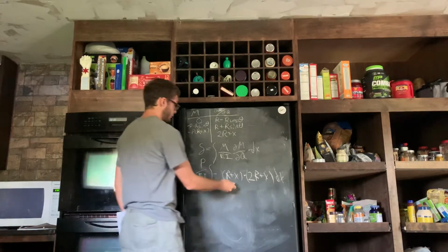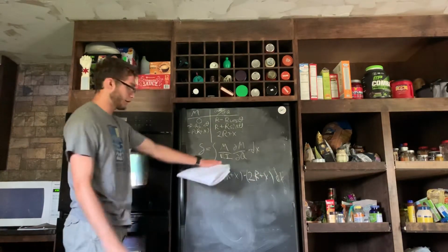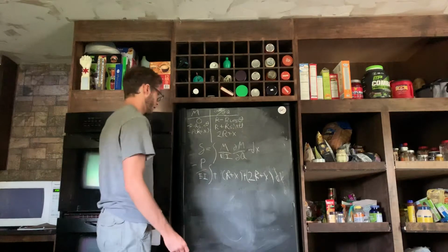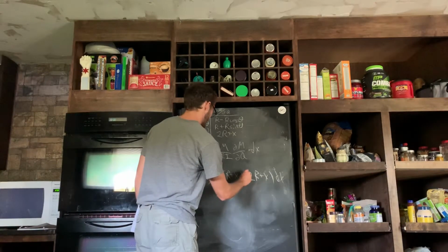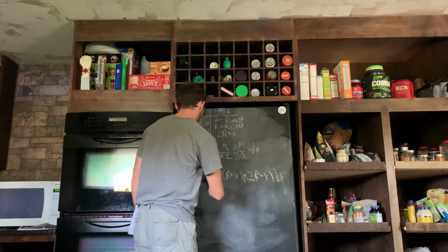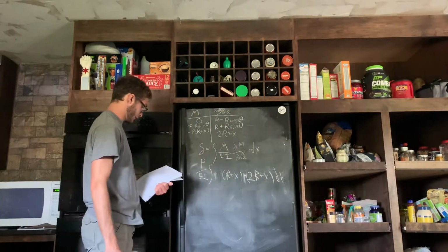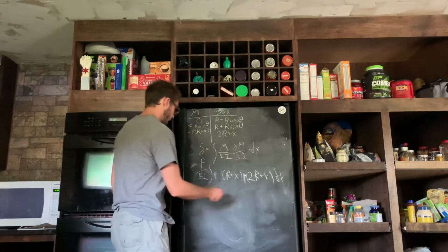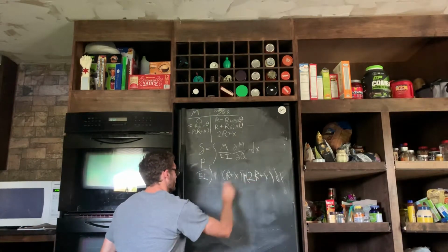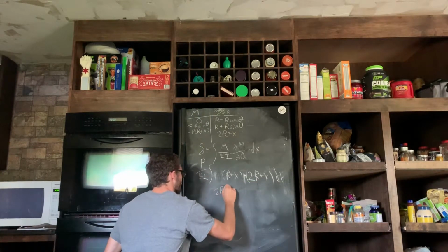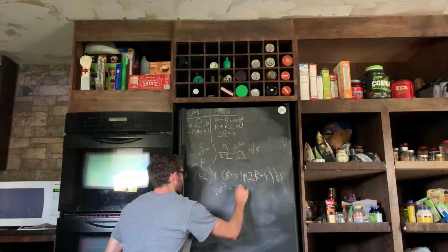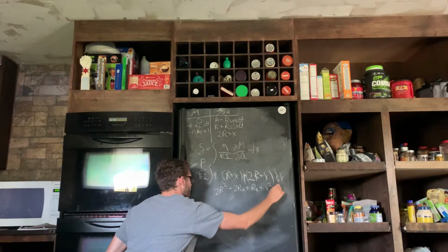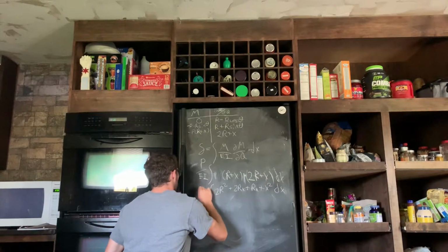So inside we have 2 equations with respect to x. They're both negative, so let's just pull out the negative sign as well, make it a little bit easy. Oh wait, no, that's a multiplication. No, it's not that, so we're going to keep the negative on the inside. So we move on to our next one, distribute. So we have 2r squared plus 2rx plus rx plus x squared dx, P over EI.